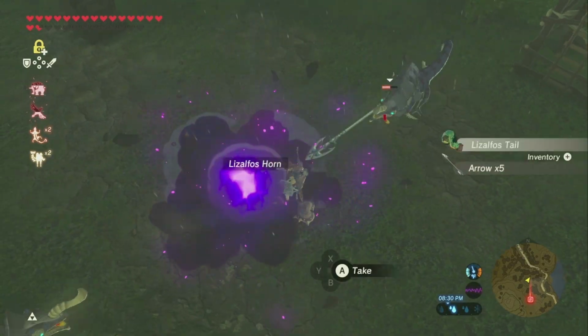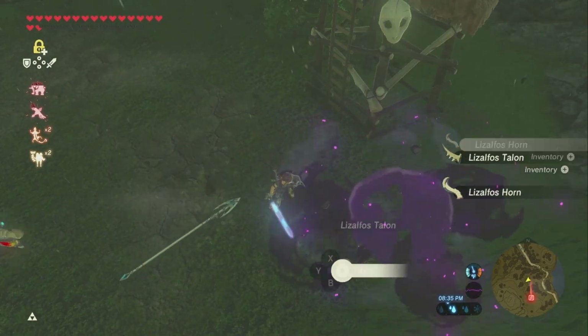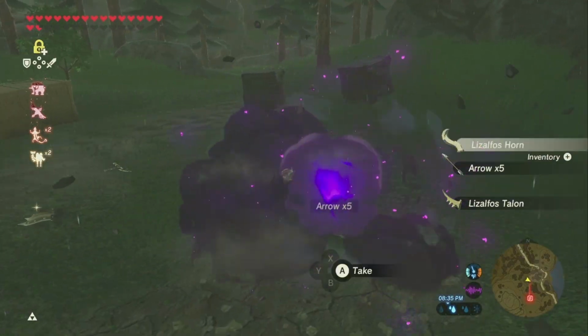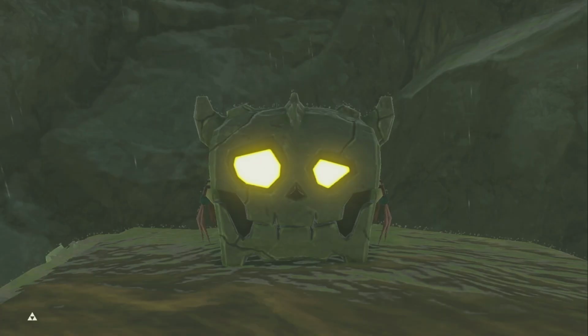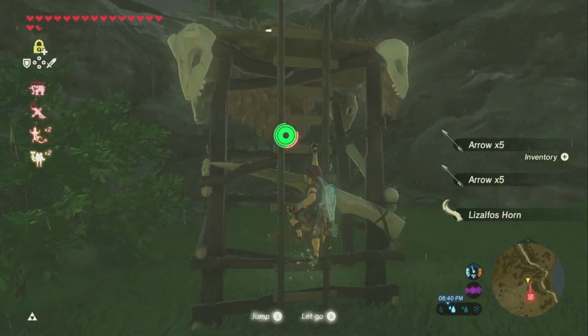Alright, equal pipe lengths. When water heaters are installed in parallel, the pipe lengths running through each water heater must be identical so that each water heater sees the same amount of water and does the same amount of work. Otherwise, one will wear out much before the other.